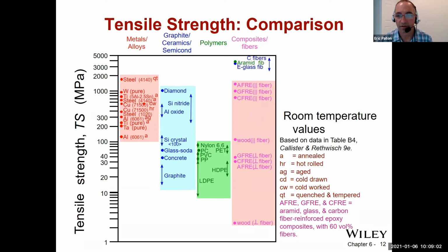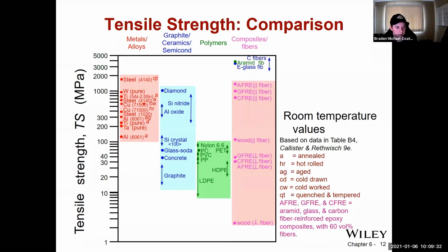But those precipitates are inhibiting dislocation motion, and dislocation motion occurs beyond the yield point, whereas stiffness is a property in the linear elastic region, which is only the area where we're stretching bonds. And so precipitates aren't going to have any impact on the stiffness of the bonds there. Okay. For the most part, yeah.